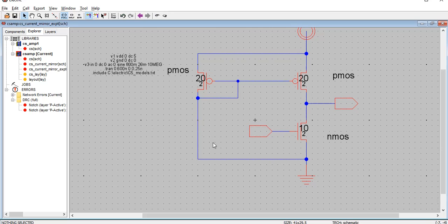So, this should be in the diode connected form, and no need to mention the current source over here, because we are not generating any current source of this value, whatever the value I am going to use. Rather, I am going to ensure whatever the current is flowing in this PMOS, the same current should be retained in the other PMOS.